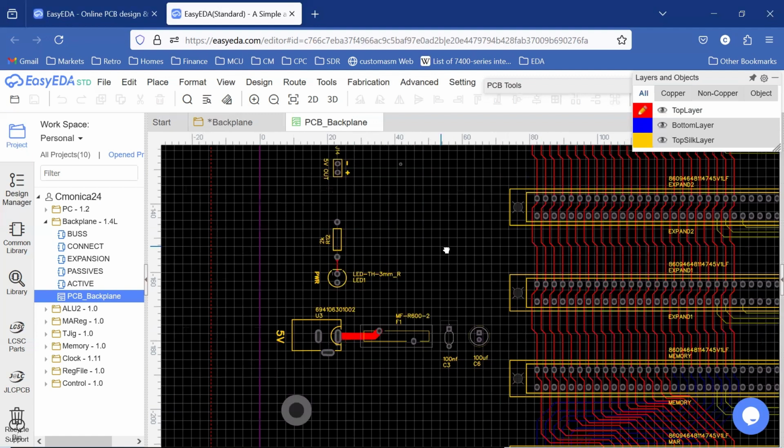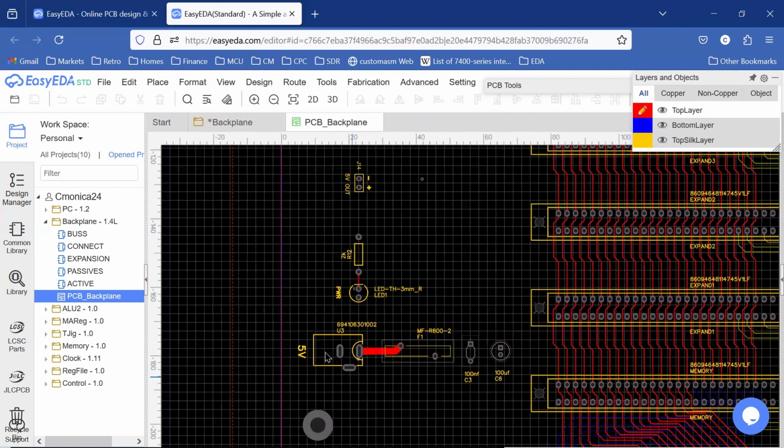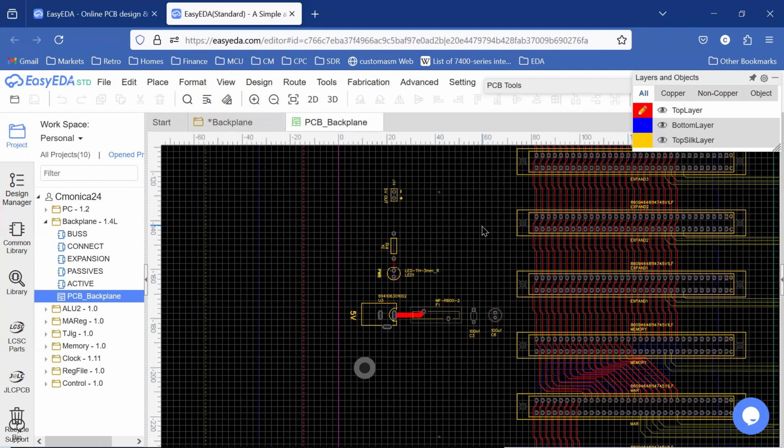Here is our power section. We have our barrel plug. We have our resettable fuse. Here's our power indicator. And I also brought out another little 5 volts out header, just as a convenient item that more than likely we're going to use, as we're going to need some power for our testing purposes for the backplane. And what else?